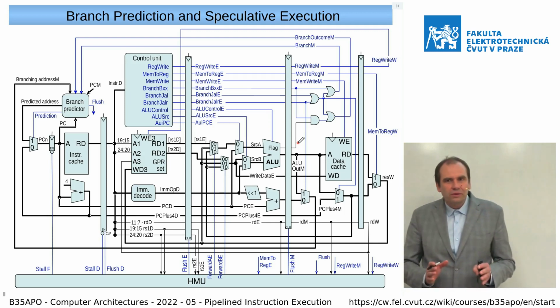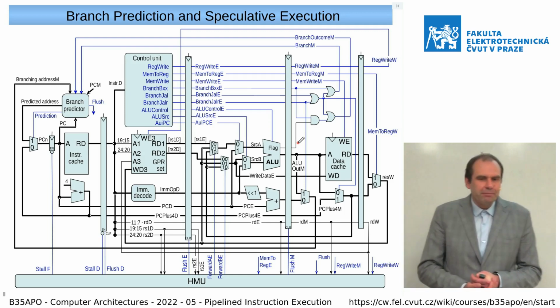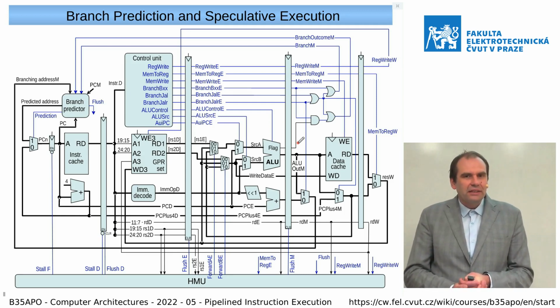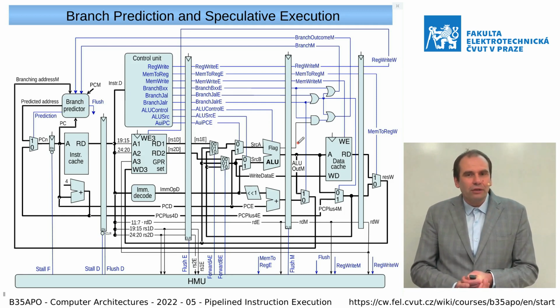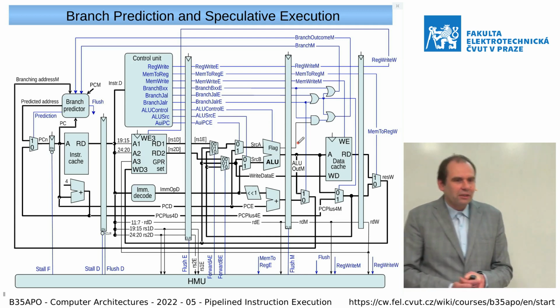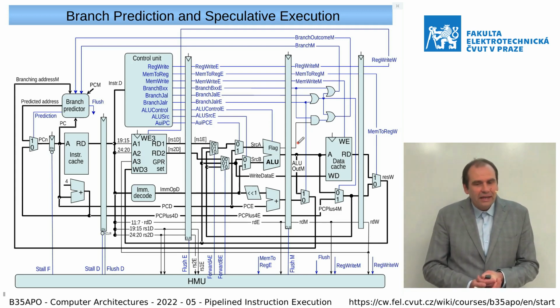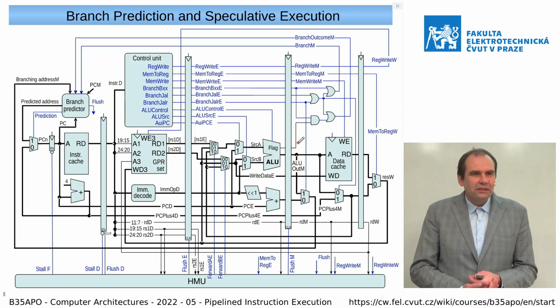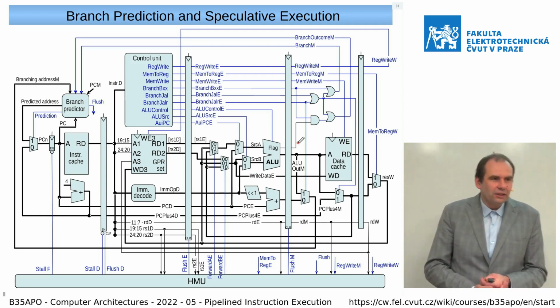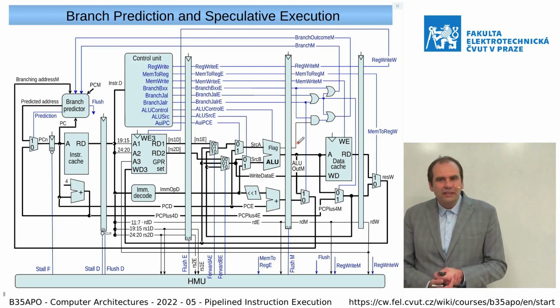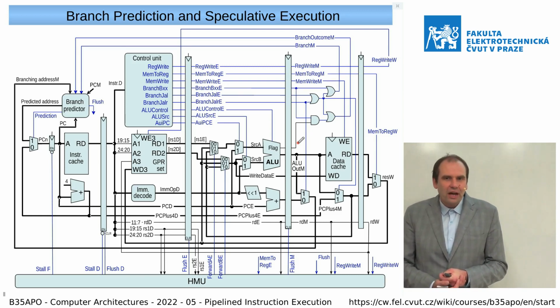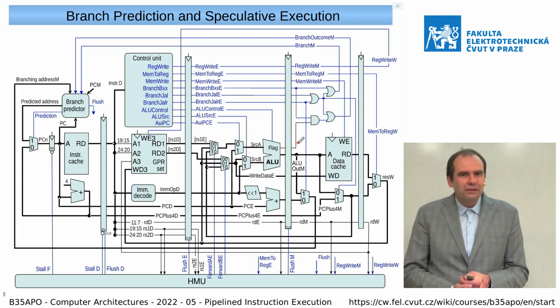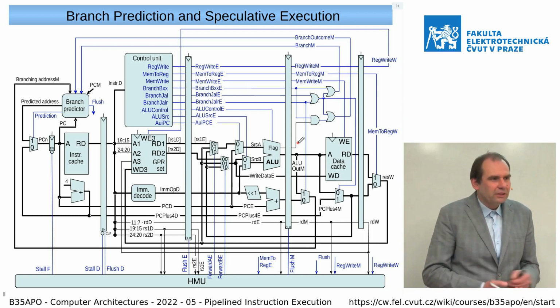If you speak today about the Apple CPU M1, then this architecture is able to decode up to 8 instructions in a single clock cycle. And it has partially processed instructions in the range of 600, something like 380 integer and up to something like 250 floating point instructions.